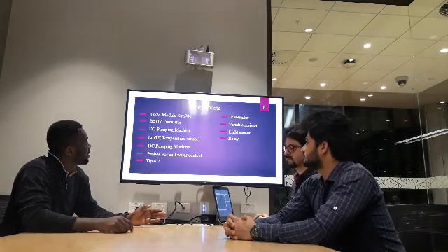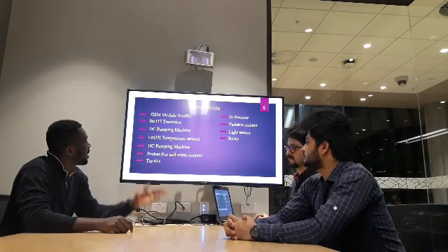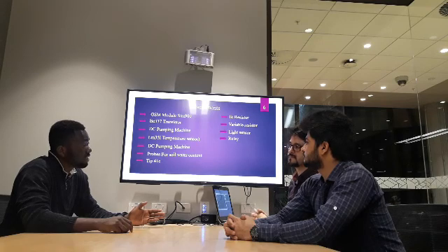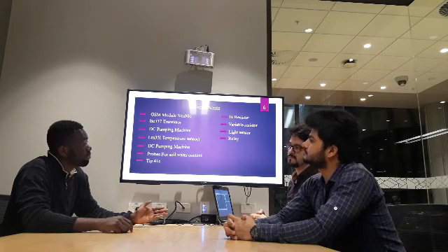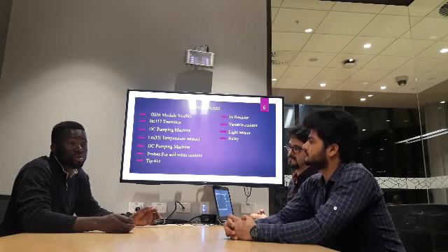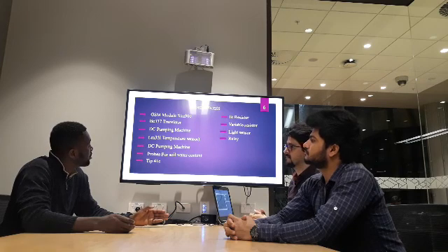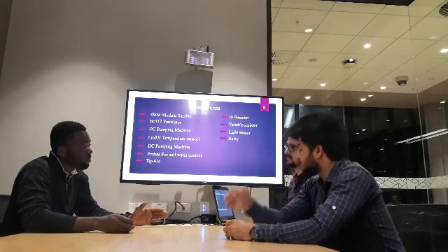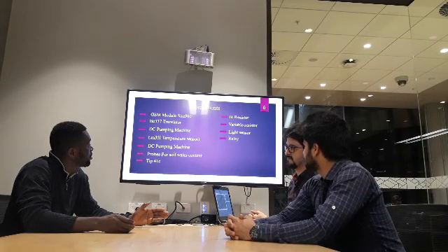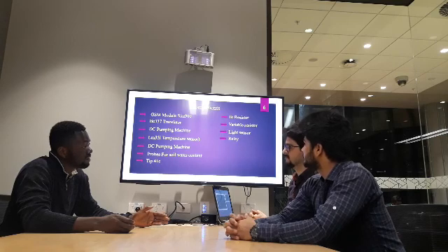The next slide is about the components, and as I have said, I've talked about the GSM module SIM 900. We're also going to use the transistor in connection with the probes, because the two probes that go to the ground will give us a negative output, which we will use with the NPN transistor. The DC motor is for pumping water from the reservoir to the farm, and we are also going to use a resistor and a relay.